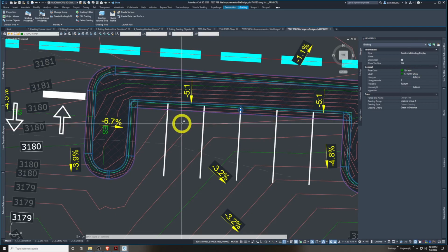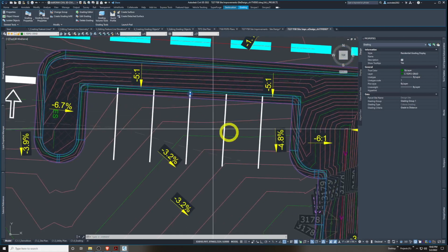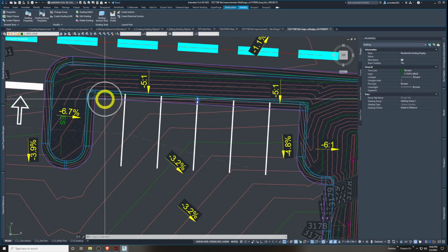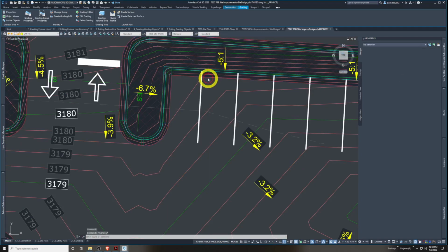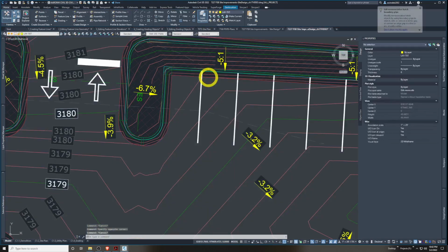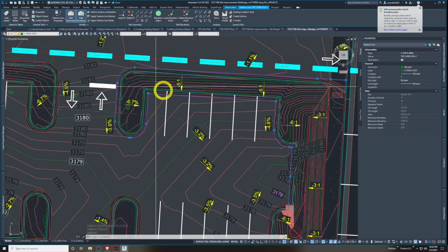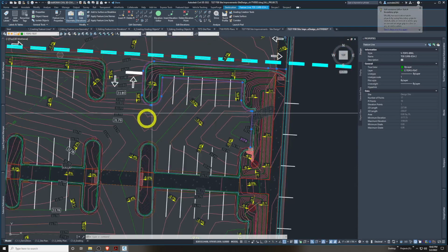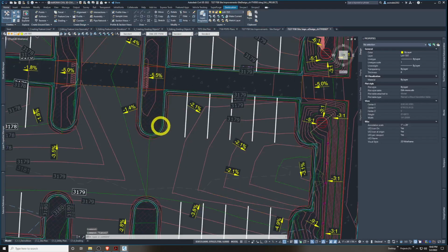I graded this as a catch or a spill curb, depending if its nose points up or down. I said I want to grade to this distance at this amount of grade, 2 feet. So I made the top back of curb really quickly once I had the toe made, and I made this all the way along all these curb islands. And basically, whenever I manipulate one feature line, the grading object moves with it. So I added a level of dynamicness to a good majority of my design here for this uniquely shaped parking lot. All these grading objects connected to my feature lines here.